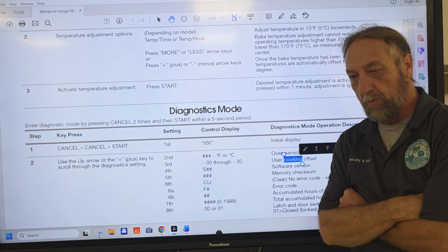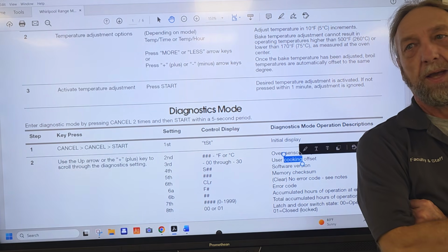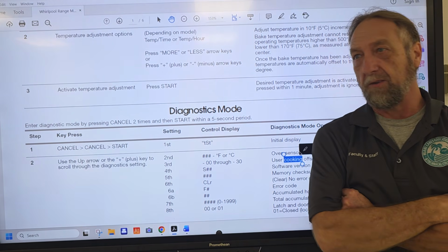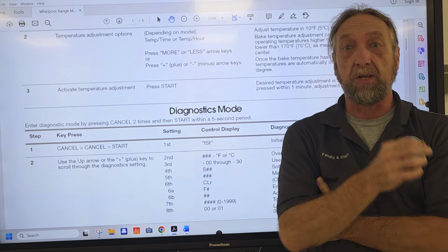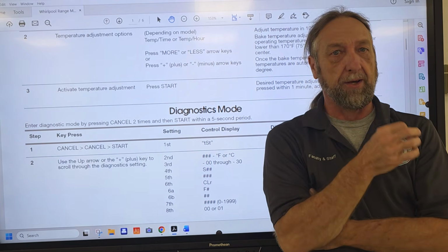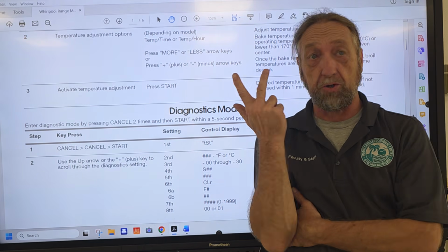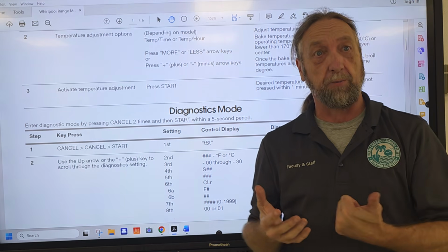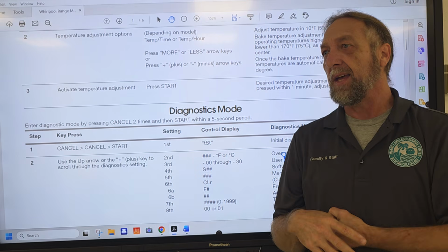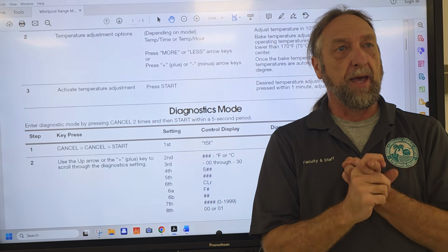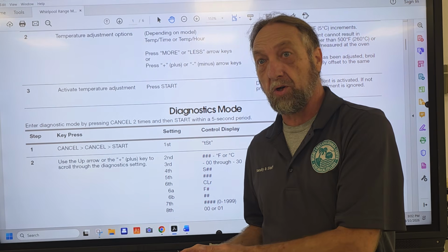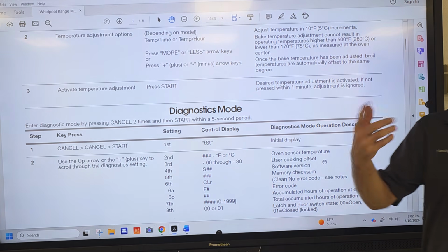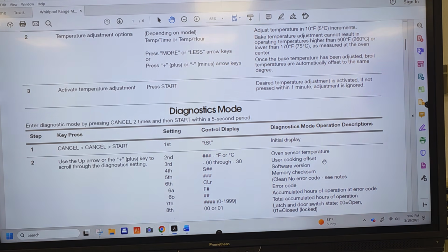So it would tell you the temperature. This temperature probe, and I've talked about these before, inside the oven, these sensors are called thermistors. Now you guys, especially the ones that are new, thermistors are in a majority of our appliances. Our dryers, our washers, our dishwashers, our refrigerators, our stoves. Dishwashers have them too, if I didn't say dishwashers. Anything that heats or cools, we have to have a way to control the temperature, and how does the board know what the temperature is? So this oven sensor is going to give you a specific reading based on the temperature. Okay,